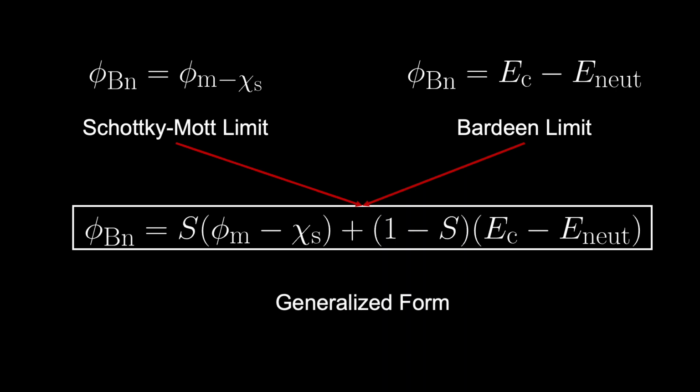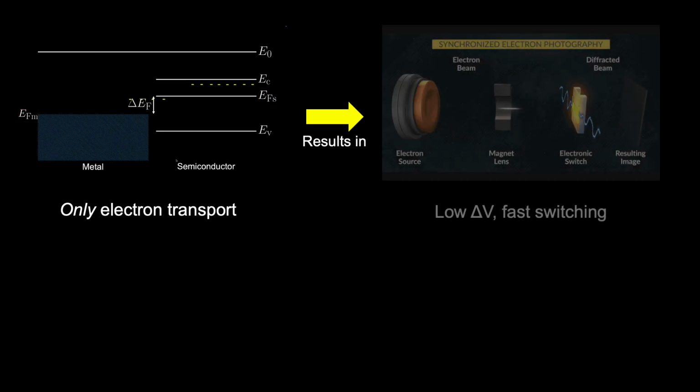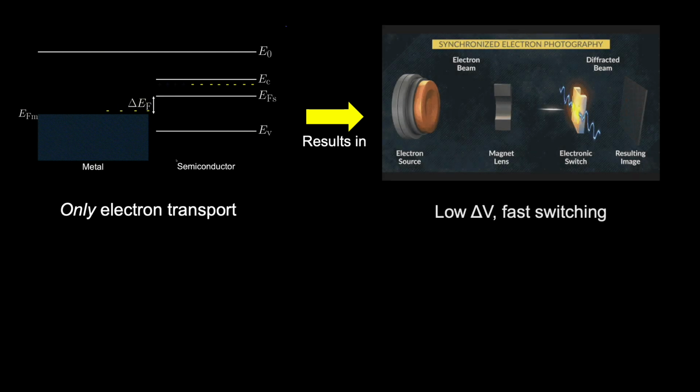Due to the Schottky barrier, metal semiconductor junctions can also function as rectifiers, commonly used in Schottky diodes. Additionally, because the Schottky barrier forms as a result of electron transport, it has a low forward voltage drop where electrons do not have to fight against drift currents, benefiting from ultra-fast switching between on and off states. This makes them suitable for use in high-frequency devices and efficient rectifiers.